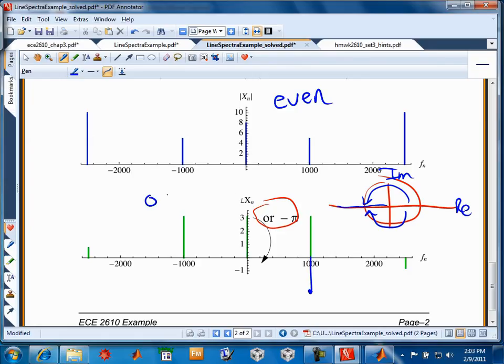In this plot down here, the phase spectral line plot is always odd. So to make it appear odd, we really should have the sticks going in opposite directions at the positive and negative frequencies, but where things break down is at pi, because pi and minus pi are equivalent to each other. So that beauty of the odd or even symmetry gets messed up.